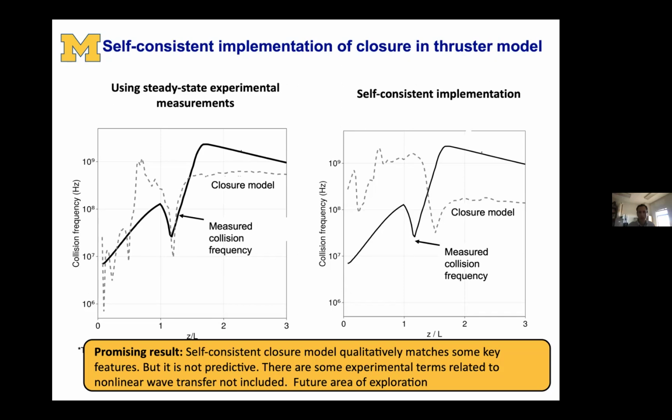And so if you're correct that anomalous transport is due to the electron-cyclotron drift instability, does this suggest paths for improvement? You mean thruster improvement? Yes. Ideally, your thruster has no electron transport because this does represent a parasitic loss. Any electrons that are transiting through the thruster don't contribute to thrust. And that's actually the dominant loss process. It lowers the efficiency by a factor of 25%.